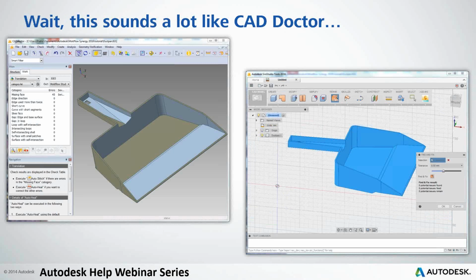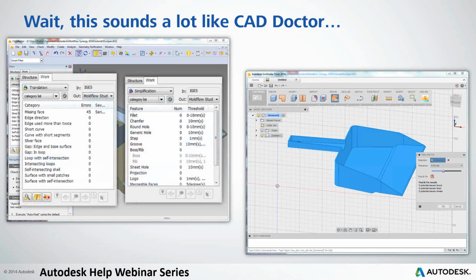So we mentioned a little bit earlier the CAD modification programs such as CAD Doctor. CAD Doctor is an Autodesk product that searches through your model for any issues that could cause trouble when meshing the model in Moldflow. And you can see it's got several different error fixing techniques, and you can even run an auto heal through that.